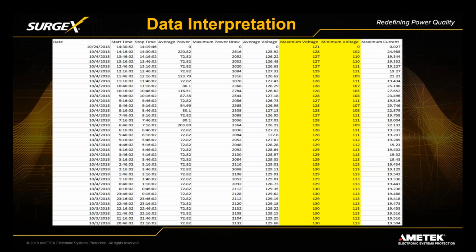And you're right, a lot of times we are able to help the customer get to the root cause, which might be wiring within the structure, or if we've had an EC confirm wiring has its integrity, we've got tight connections everywhere, we're not missing ground, we've got bonded neutrals that are proper. We're finding that it's the utility. We've had corroded transformers, we've had loose neutrals in the transformers. Then here our integrator is being held feet to the fire because guess what? It's his or her audio video product, those devices in the system that don't seem to be working. So it's been huge. It's been from minor to very major, getting customers out of actual litigation. So it's been pretty big.